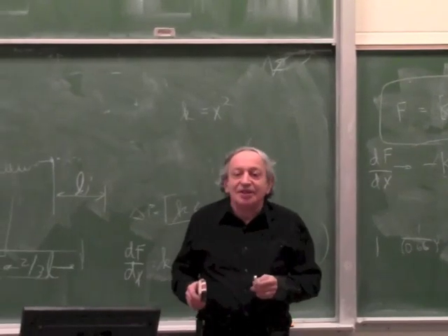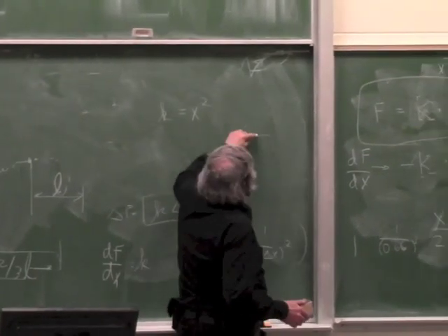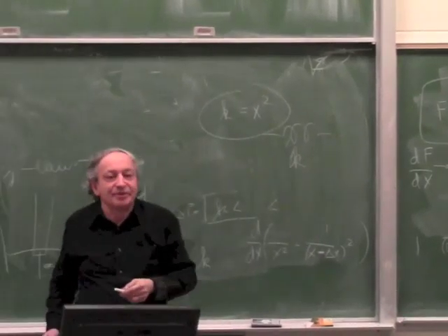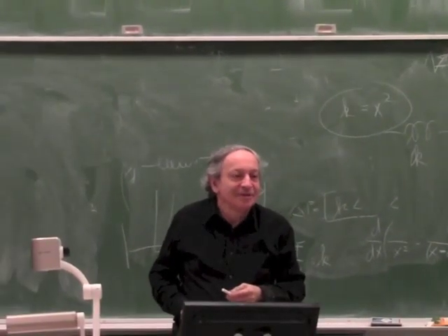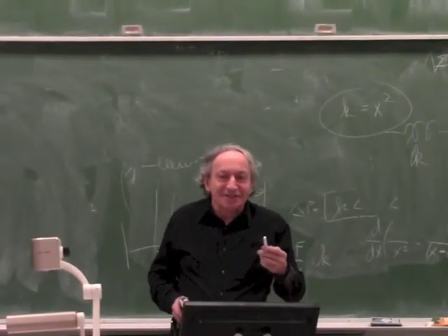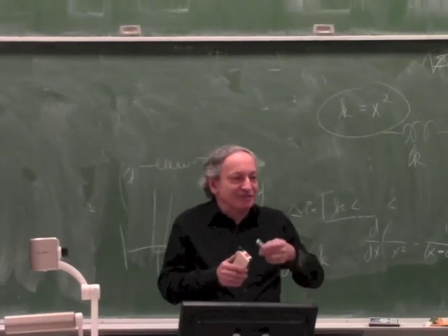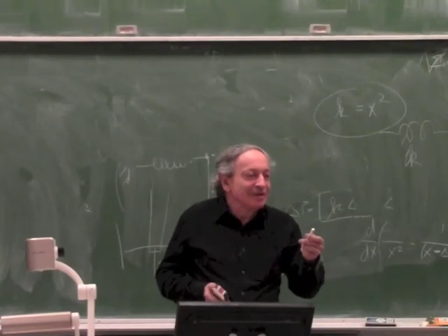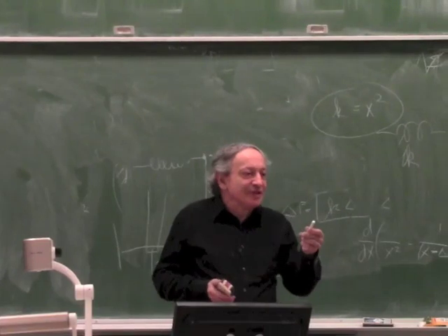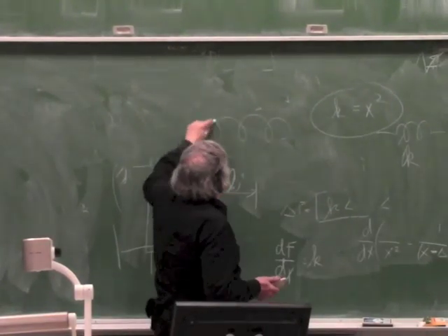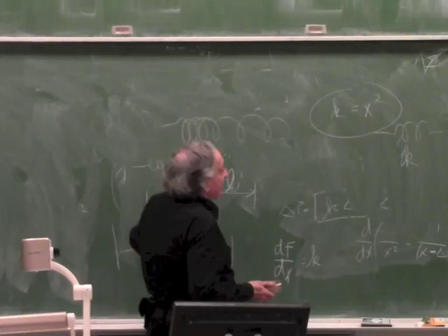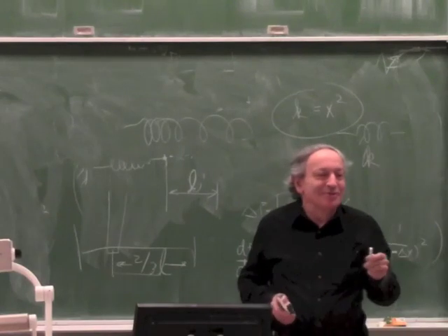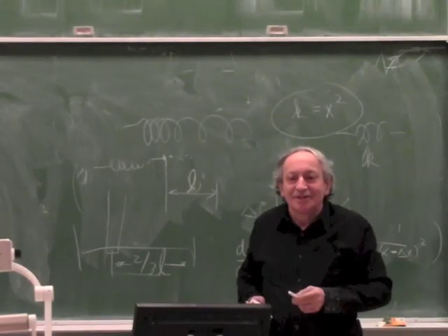Now, can somebody think how you make a nonlinear spring? If you take a normal spring, it's a constant k. How do you make a spring where k is not constant but x squared? Varying thickness or diameter? Physically, varying thickness is difficult. You could vary the pitch of the helix, but if you just vary the pitch of the helix, it's still linear. There's no effect on k. There are a few simple tricks to make a nonlinear spring. When they touch. Ah, beautiful.